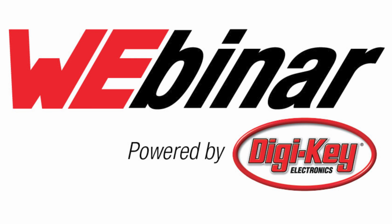What is the wall plug efficiency? Something around 3%. These UVC LEDs are quite a new technology. A couple of years ago it was much lower, but the coronavirus mainly boosted the technology for UVC. Since the start of the coronavirus, you have already seen a lot of increase in the wall plug efficiency. Currently it's something like 3%, but it will definitely go up in the future. It might take a few years to reach values similar to other LEDs.